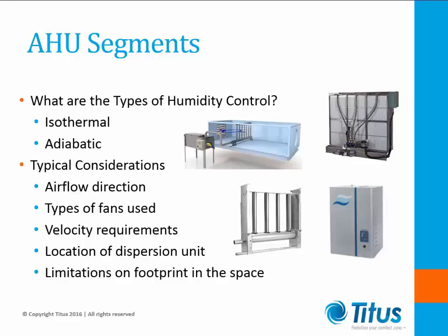With regard to proximity, changes in direction of airflow, for example, in a vertically configured air handler, may require larger segments immediately upstream and downstream of the humidifier segment, affecting the overall footprint in the mechanical space. Providing factory-installed equipment within the air handler lowers the cost of field installations of the humidifiers and keeps moisture out of the supply duct.